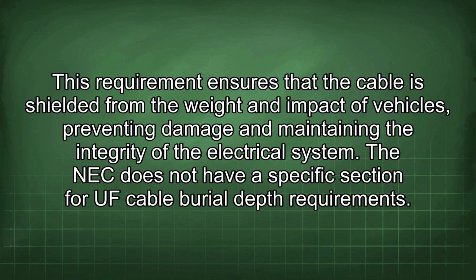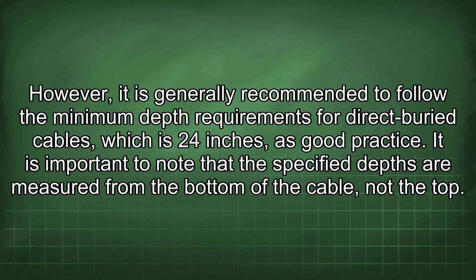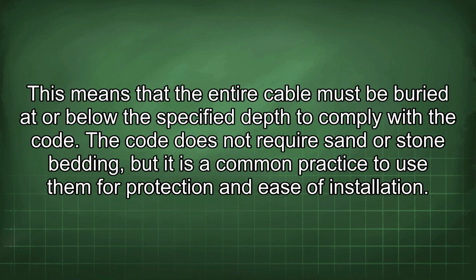The NEC does not have a specific section for UF cable burial depth requirements. However, it is generally recommended to follow the minimum depth requirements for direct buried cables, which is 24 inches, as good practice. It is important to note that the specified depths are measured from the bottom of the cable, not the top. This means that the entire cable must be buried at or below the specified depth to comply with the code.